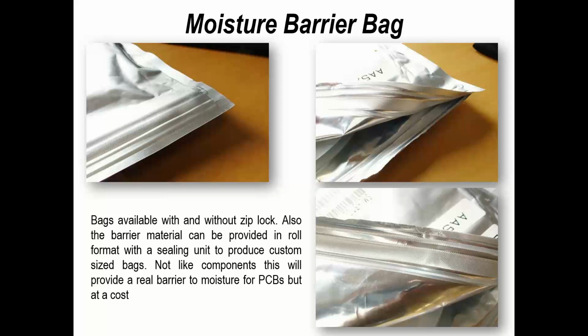If we talk about board finishes, we have multiple different types of board finish. If we are using gold or tin lead boards, or lead-free solder level boards, then it's all about the thickness of that solder coating on the boards. So if you have 2 microns, you might get less than a year. If you've got 10, 15 microns, you might get more than 2 years.